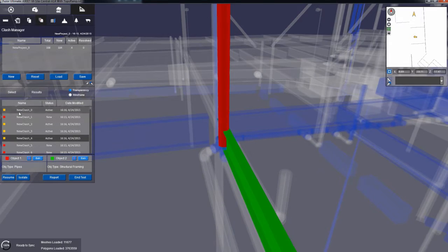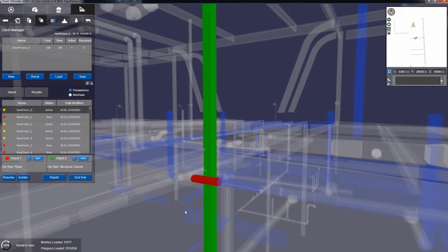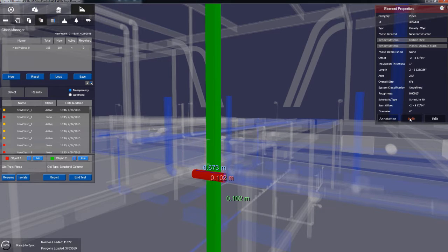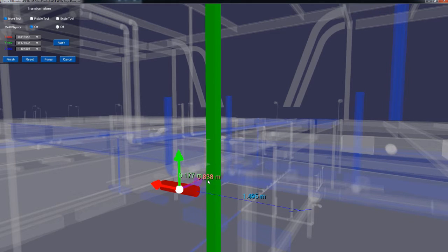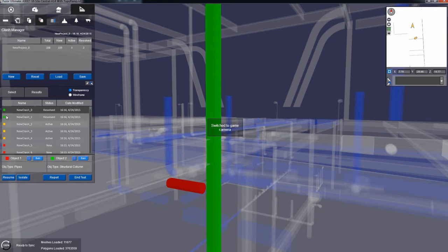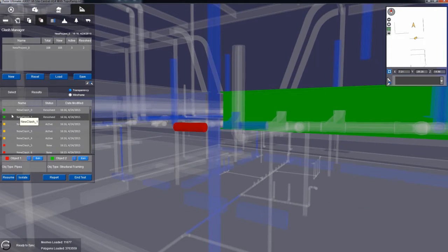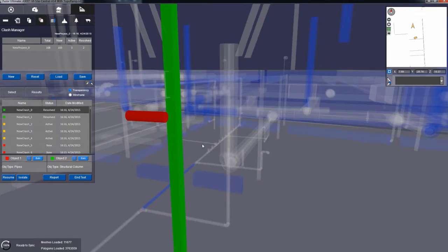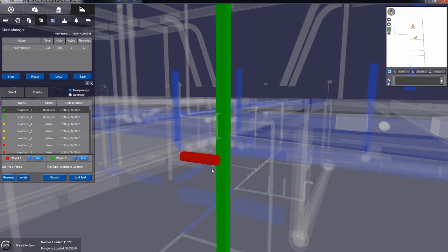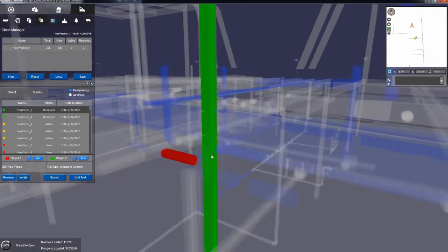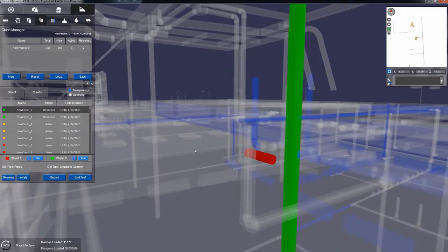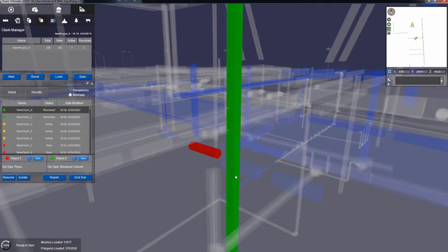Now, just FYI, you do have the ability, assuming you are the MEP guy or gal or whatever, to refit, and by doing that it will actually clear that clash and any associated clash, like so. Now personally, coming from a construction management standpoint, I really would not recommend that unless you are the MEP person. You don't know what disconnects you may be making, or even what additional clashes you may be creating.